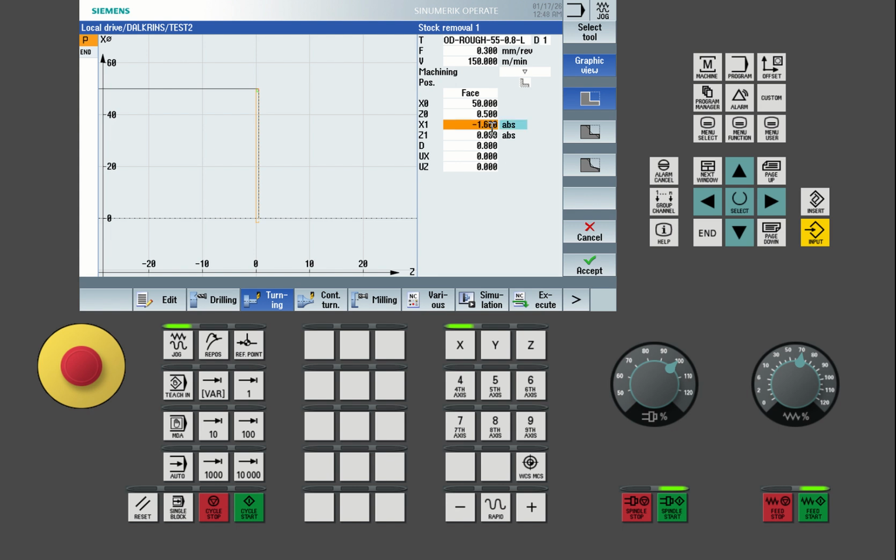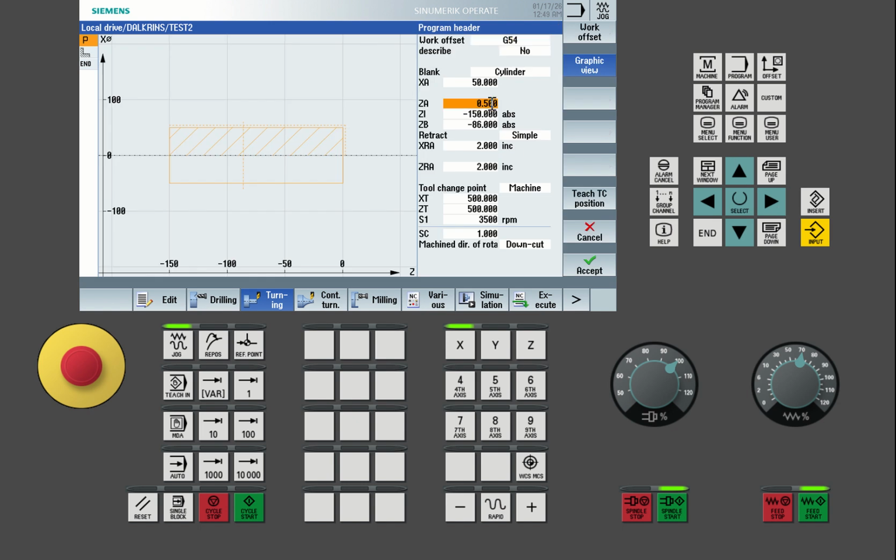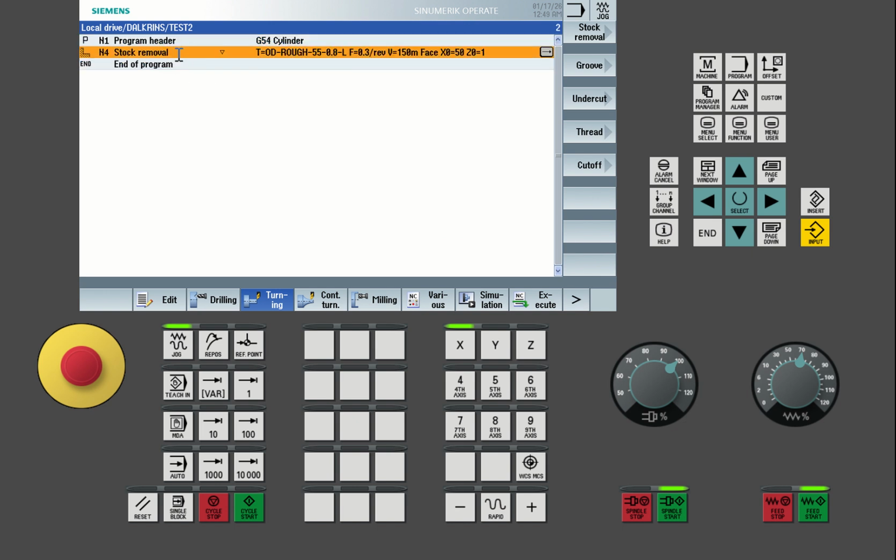And then here the amount to cut beyond this region. You see this region. Here I can put 0.25, half of this one, or this one I can put 1. But remember, if I put 1, I have to put a smaller value here, maybe 0.3. Okay, then accept. But I will have to come back to this one, because the amount of face was 1, so it should be the same. Accept. Then from here you want to go to contour editor.